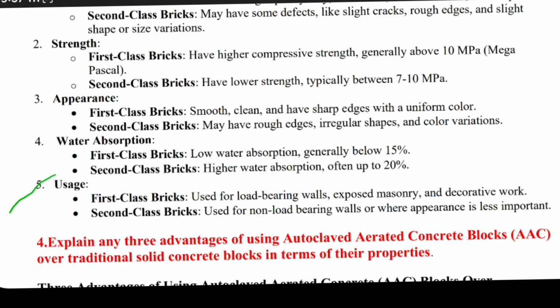The next property is usage, that is, where you have to use them. First class bricks we use for load bearing walls, exposed masonry and decorative works. Second class bricks we can use for non-load bearing walls, where the load is very low and appearance is not important.